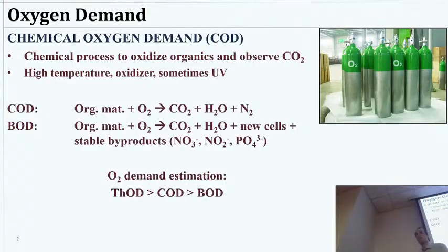So if you have some molecules like that, or with some nature that is similar, maybe they'll resist oxidation under the conditions we give it. And so they will not consume oxygen. They will not be counted in a chemical test to see if we put in certain chemicals. Now this will overestimate the real BOD, but sometimes it's quite useful.